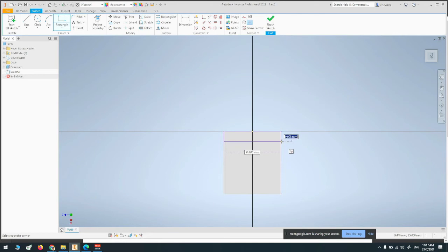What I'm doing here is I'm drawing the rectangle, and I've told Inventor that I want this point to be on this line here and the next point to be here. So this means whatever width this one is going to be, if next time I want to change it, this rectangle is also going to follow. So that's one of the powers of constraints. By relating one line to the next line, we're able to make the drawing update automatically.